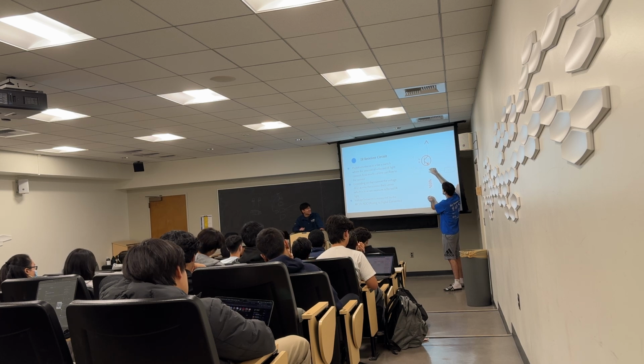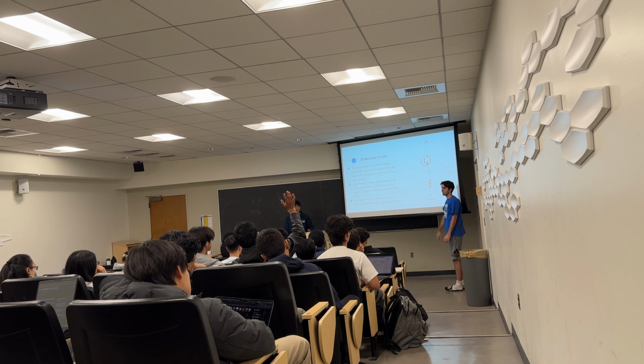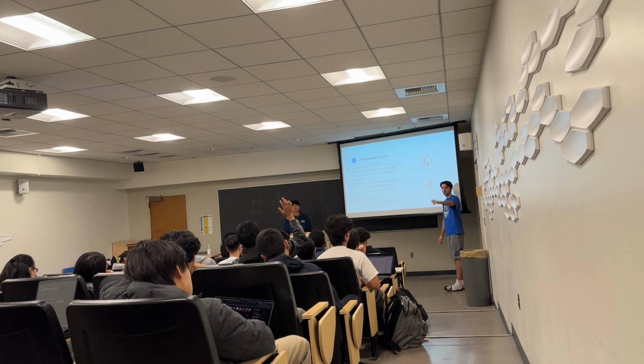But basically, if we increase I in V equals IR, the voltage here is going to be greater, or the voltage drop across this, because this is ground, which is 0, is going to be greater. And then we can measure that, which out, by the way, is going to our MCU's ADC, analog to digital converter. And that's how we're going to read the sensor.